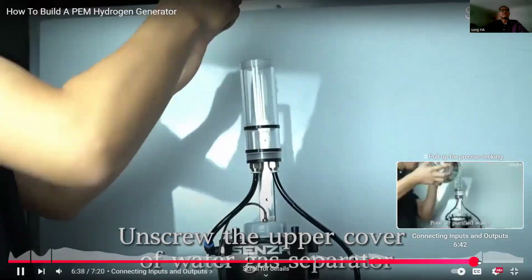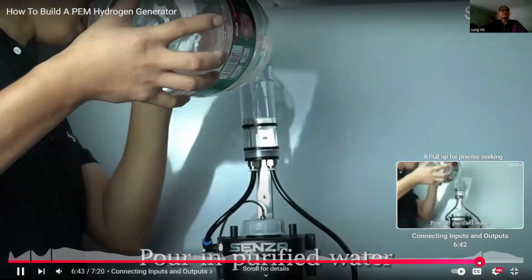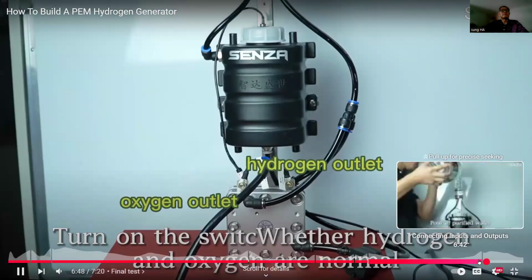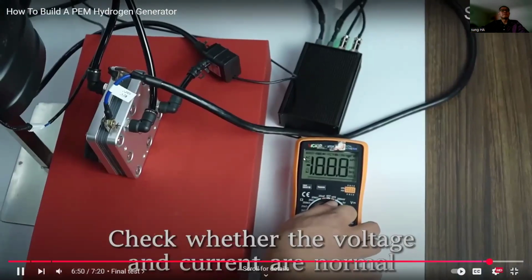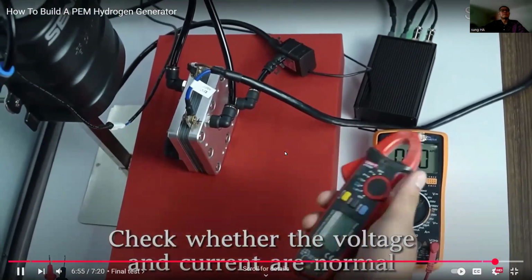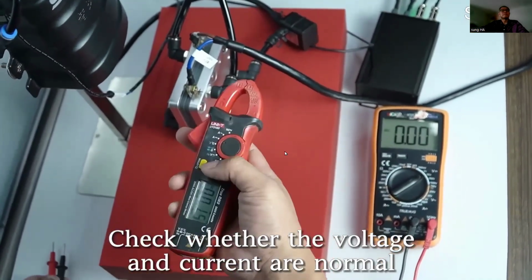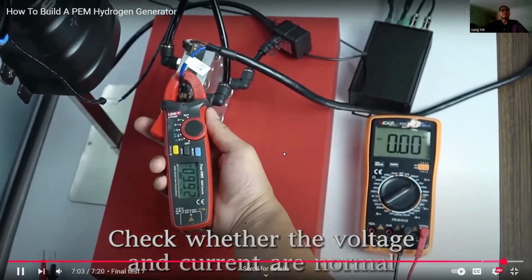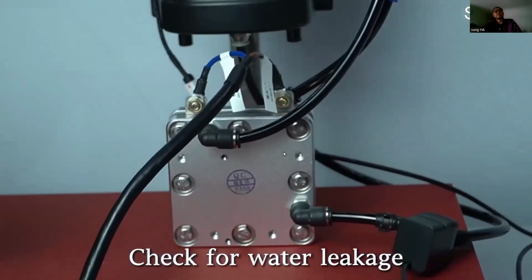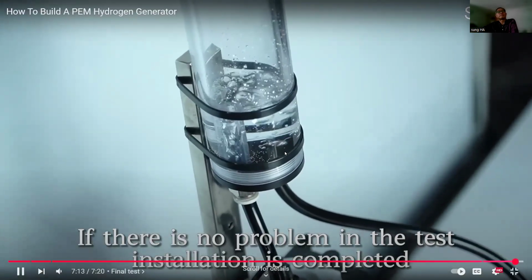Unscrew the upper cover of water gas separator. Pour in purified water. Turn on the switch. During inspection, check whether hydrogen and oxygen are normal. Check whether the voltage and current are normal. Check for water leakage. If there is no problem in the test, installation is completed.